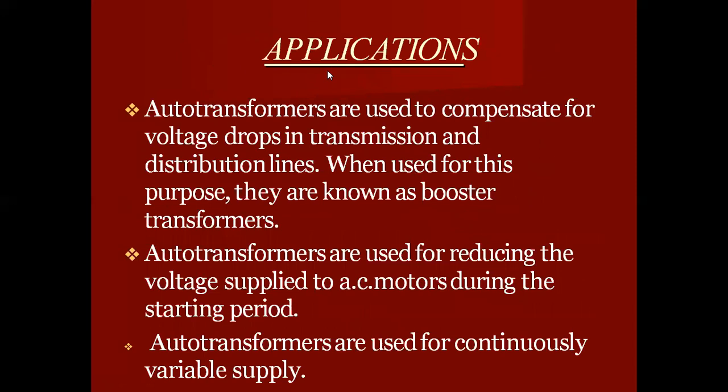So the applications: autotransformers are used to compensate for voltage drop in transmission and distribution lines. When used for this purpose, they are known as booster transformers. Autotransformers are used for reducing the voltage supplied to AC motors during the starting period. Autotransformers are used for continuously variable supply.